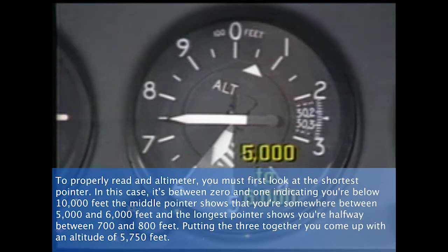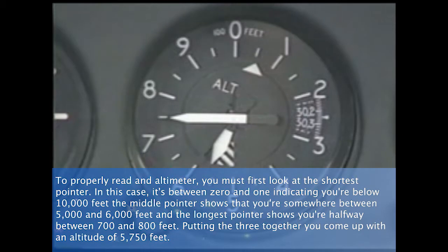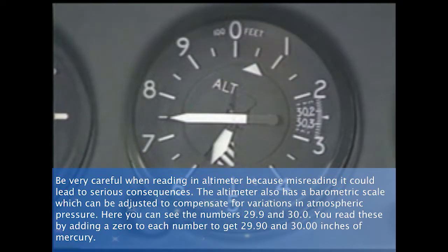The middle pointer shows that you're somewhere between 5,000 and 6,000 feet. And the longest pointer shows you're halfway between 700 and 800 feet. Putting the three together, you come up with an altitude of 5,750 feet. Be very careful when reading an altimeter because misreading it could lead to serious consequences.